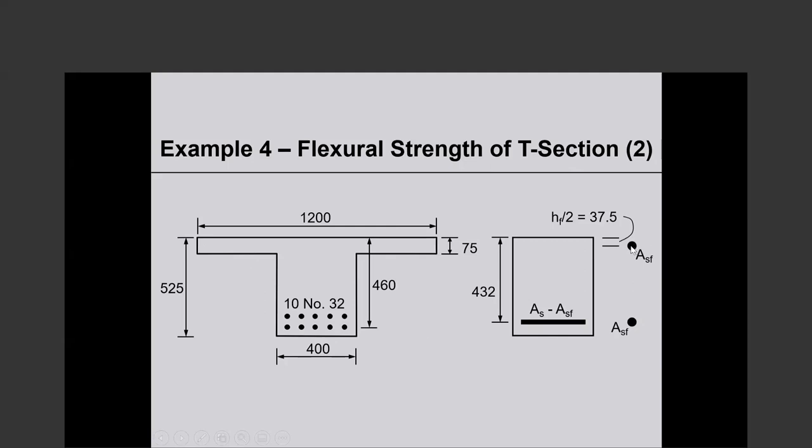So that is a steel reinforcement area equivalent to the overhanging flanges. We will consider the same area of tension reinforcement where the tension reinforcement is actually located, and if we take those out, that will leave us with a rectangular section where there is only tension reinforcement, and the tension reinforcement area is the total tension reinforcement area minus whatever we have removed. I think this is a pretty clear concept.